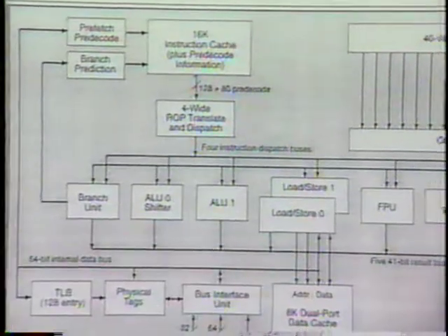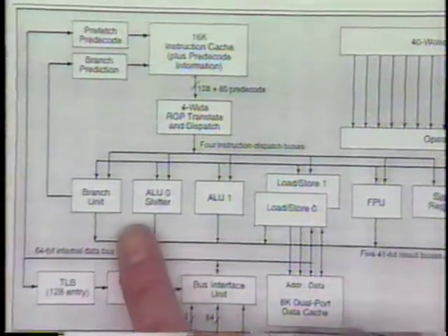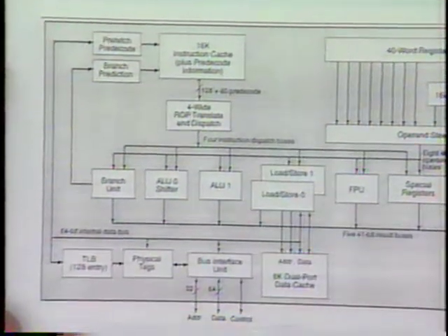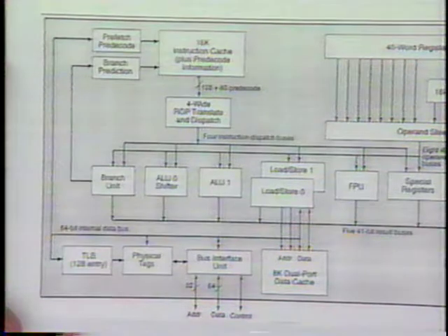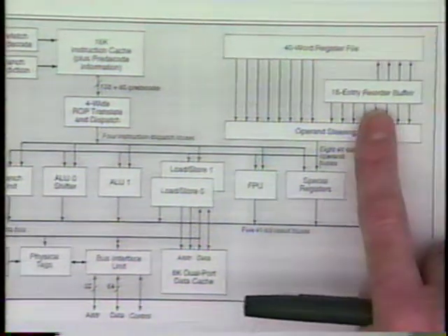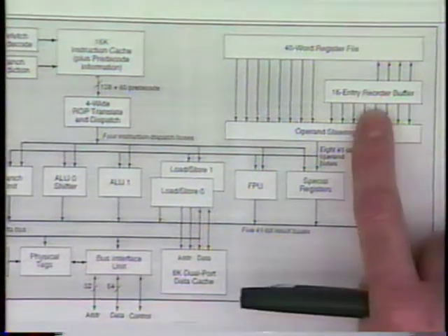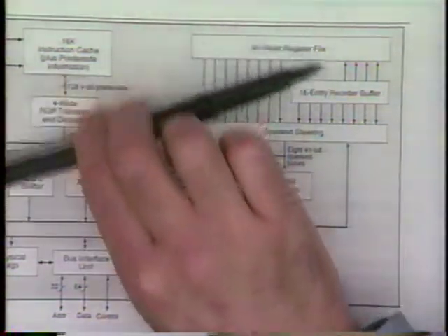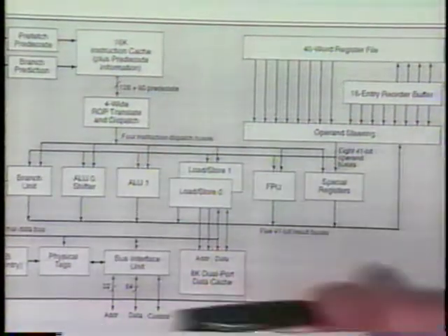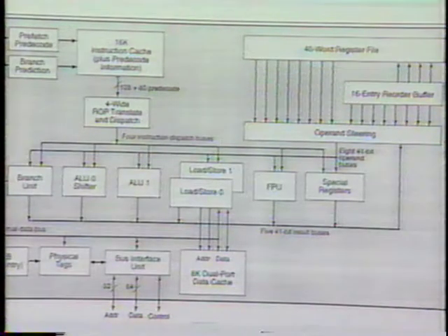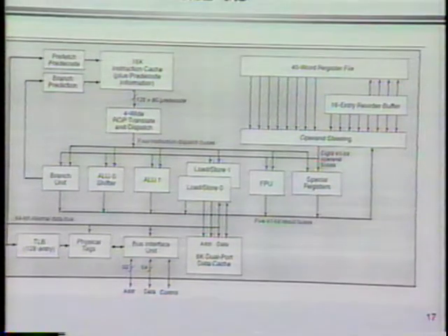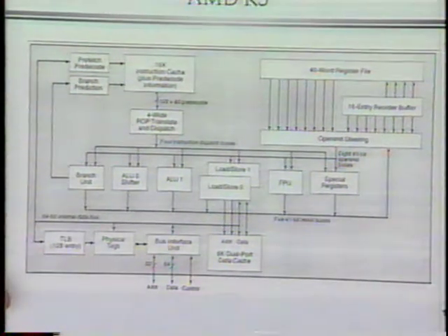They have multiple functional units. Functional units can execute in parallel. They have more than one load store unit, and so forth. They allow out-of-order execution. There's a reorder buffer that controls writing words back into the register file. Basically, this 80% of the machine is a standard RISC high-performance pipelined speculative execution machine. And this part of it up here is the part of it that efficiently translates the x86 instruction set to RISC operations.